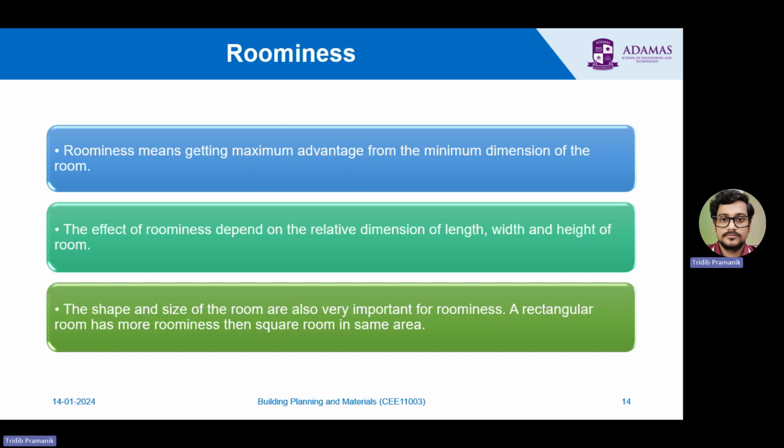It creates some uneasiness to the users. So our aim will be to maintain the straightness of the walls. If there is any such wall which has some curved shape, we should provide it either in any lobby or in the veranda or in these places.